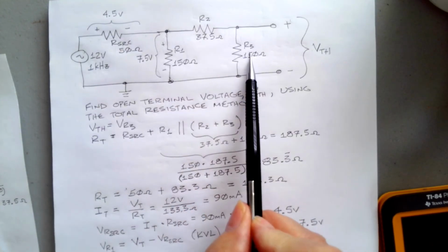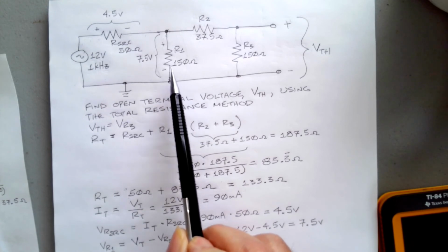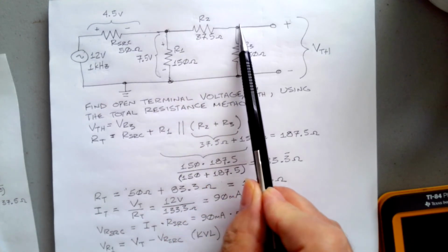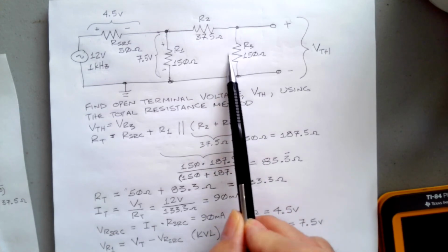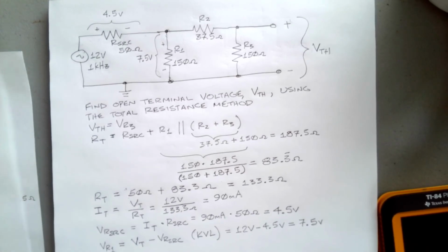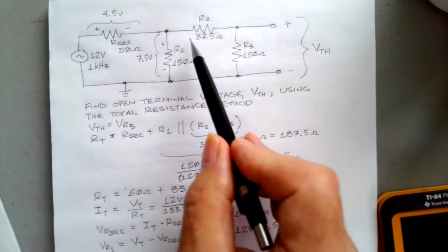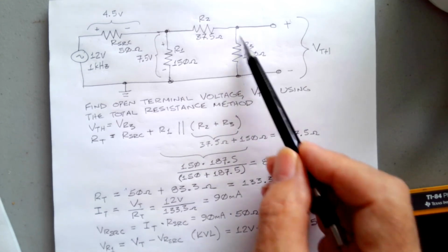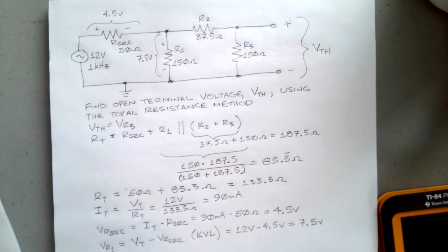So we now know from our voltage divider effect that we should be able to calculate the voltage at the load. So let's try to do that. In the voltage divider rule, now we can do this as a series circuit here with a current flowing and multiply the current times this resistor. The voltage divider rule does that very thing.